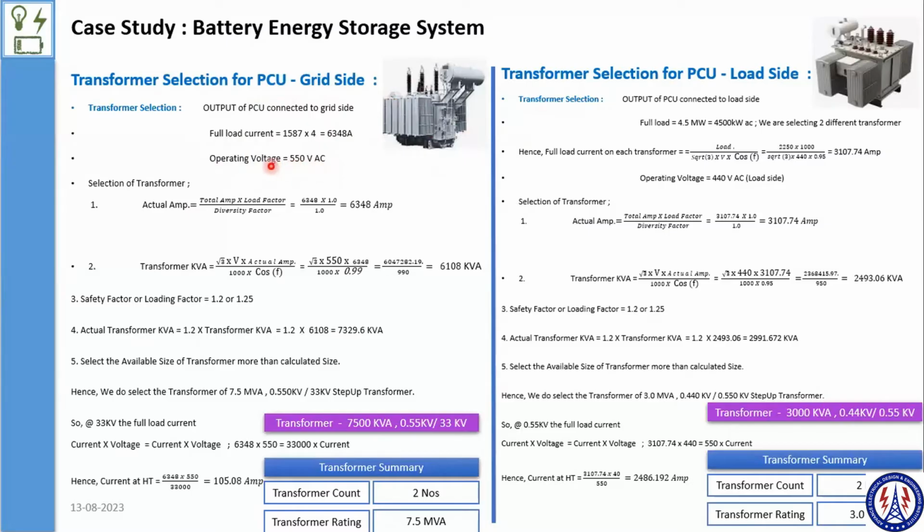Okay, it is from the PCU. Got it. I was talking about the DC plant side. For the PCU, I believe it is 4 because this is the current value of the PCU. And why 4? Because internally the PCU has 4 DC inputs, and each rating is divided equally. If you refer to this diagram again,